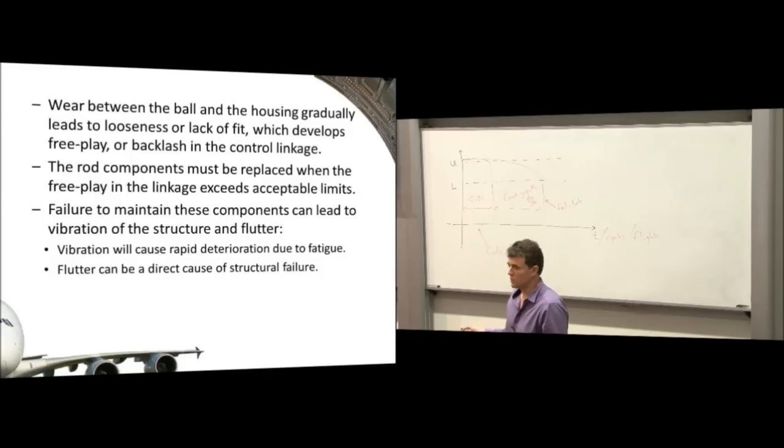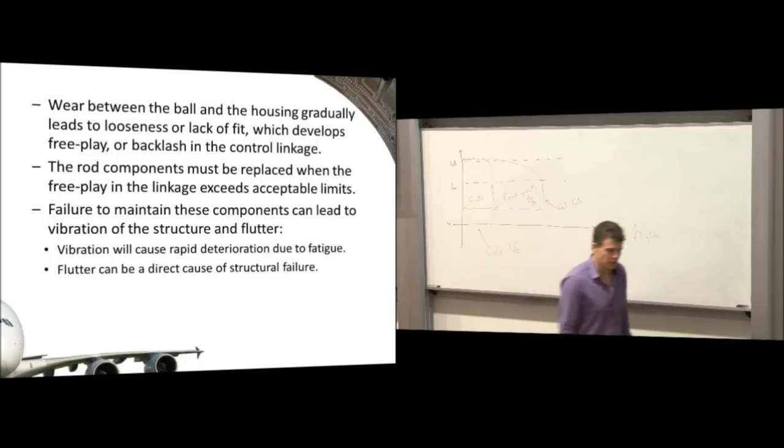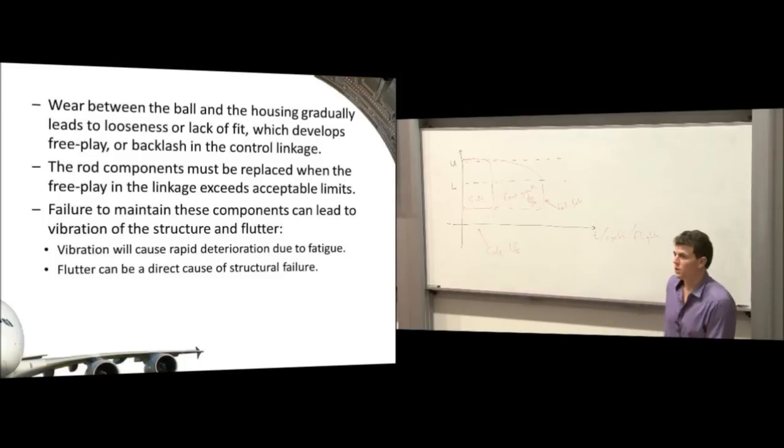And that sounds unlikely, but it's actually very, very common. It's a problem that you have to put a lot of design effort into the aircraft to stop it from happening. And free play in linkages accelerates the rate at which that flutter will occur. So we try and avoid wear in those settings.